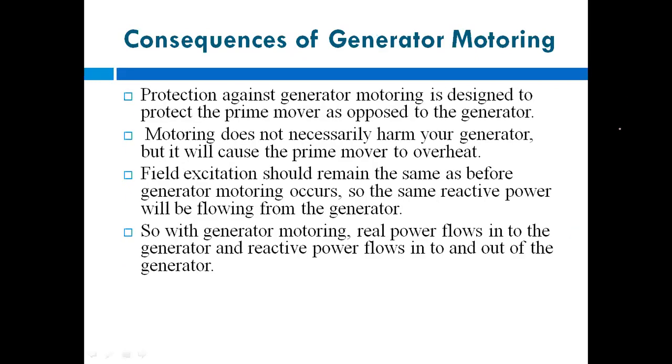The next point is the consequences of this generator motoring. When your generator goes into the motoring state, this protection against generator motoring is designed to protect the prime mover as opposed to the generator. It is used to protect the prime mover.